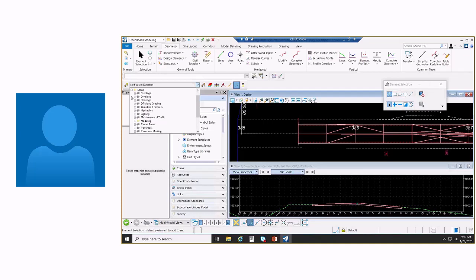So at this point, we haven't done that. So what I'm using is a feature that's just a scratch feature. So under the modeling group, so I'm looking at linear features under modeling, under the template features, there is a scratch group. So I'm just going to use this scratch 1. And I'm going to assign that as the feature on these two elements.